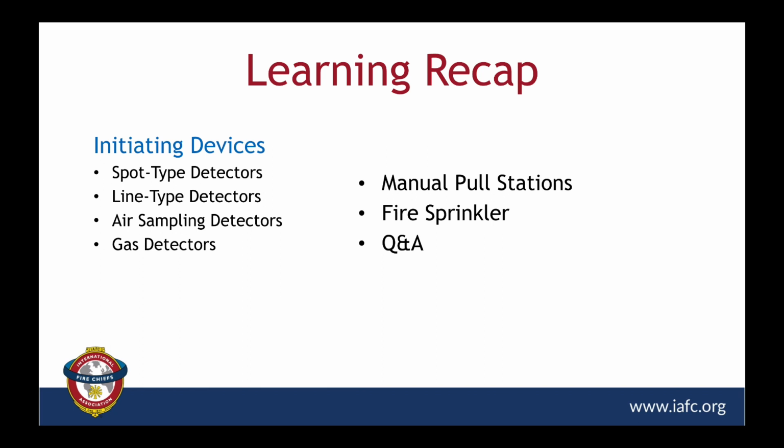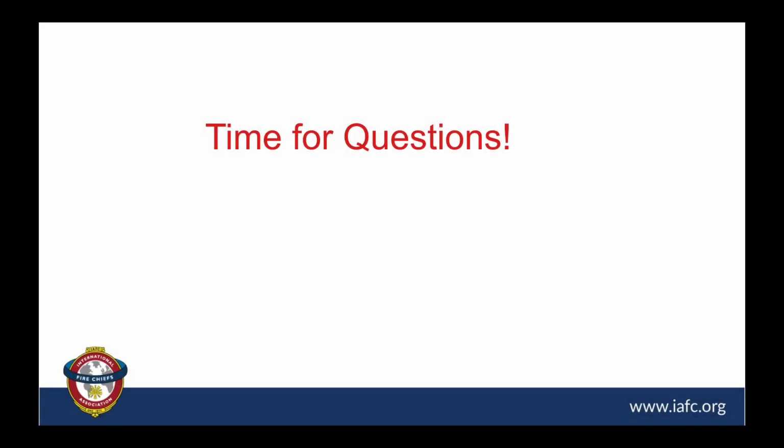Yeah, I touched on that. I didn't really elaborate on it, but there's what they call a retard setting, and you can delay the activation of an alarm. I think it's up to 90 seconds, and that is to allow for normal surges or water movement. So if you're getting a lot of that in a particular jurisdiction, you may want to dial in the most allowable time delay possible. But I think the maximum could go up to 90 seconds. But yes, there is a way to adjust that.